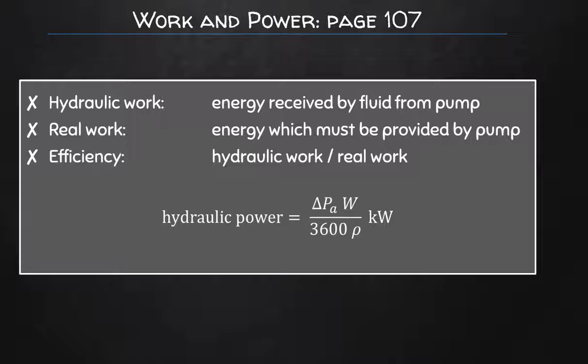Now, since W has units of kilogram per hour, we divide by 3,600 seconds per hour to complete the calculation shown. This calculation is useful as the pump characteristics specified by the manufacturer may not always be realized in your system. It all depends on the fluid in question and the operating conditions, of course. And so a quick check of the efficiency is therefore completed manually using this equation.